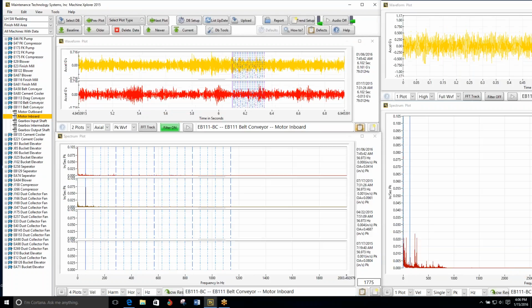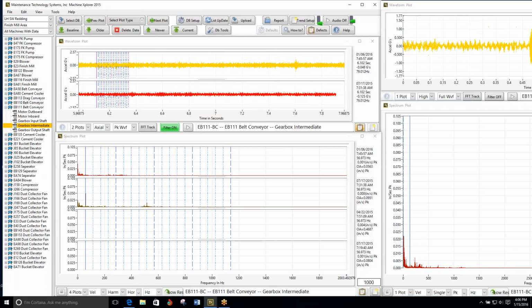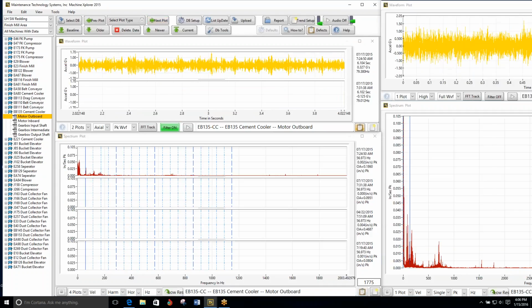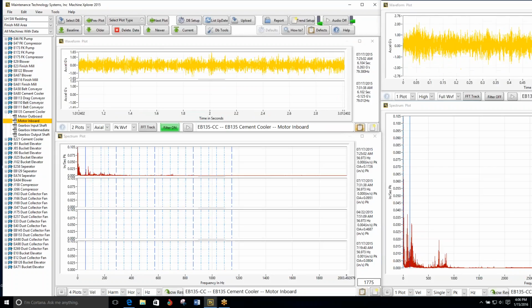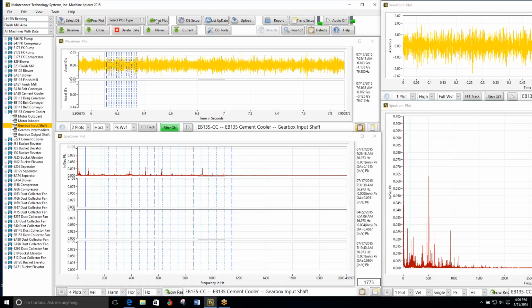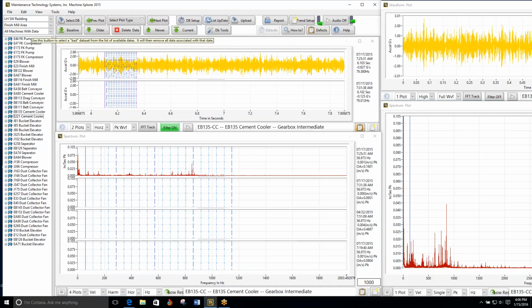My problem is I did those Syntac air compressors, and they wanted a lot of accuracy on it, and it takes a lot of time, so I really picked stuff apart. Well, that's not necessarily a bad thing, because the Syntac air compressor is a whole different animal than a little simple belt conveyor gearbox. From initiation of a significant fault to wreck just isn't very long. So you need to know where each one of those peaks in that spectrum belongs, and there's a lot of them.